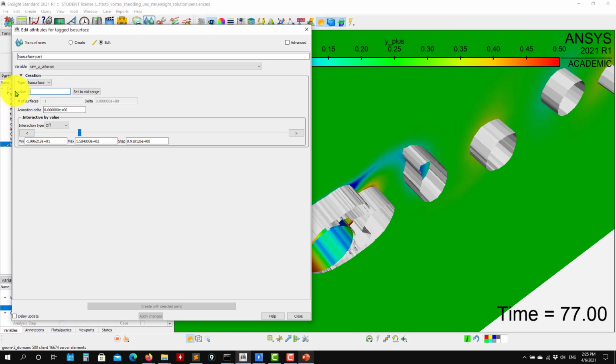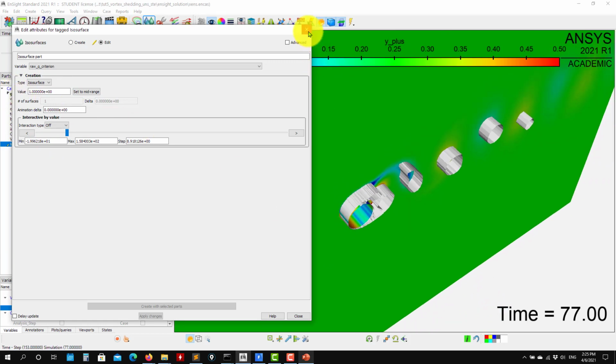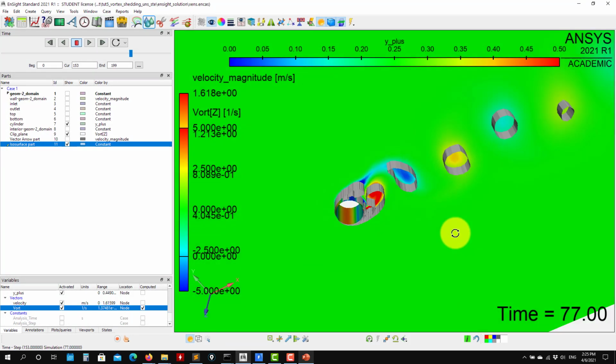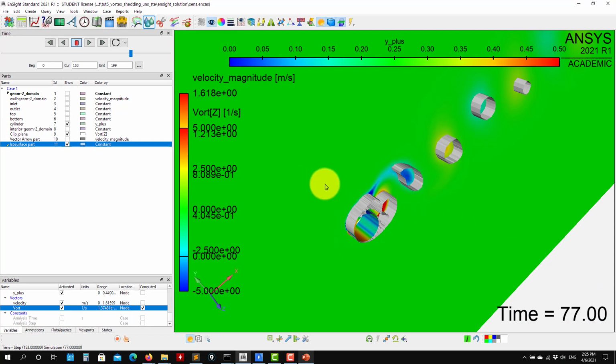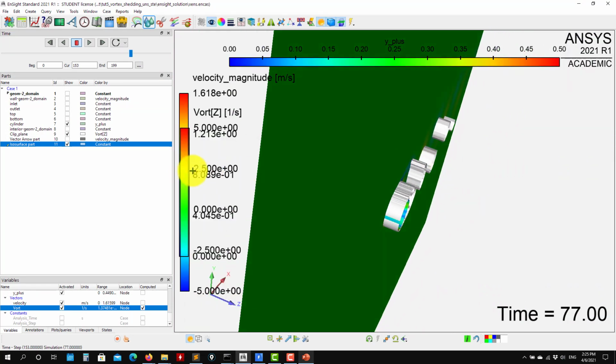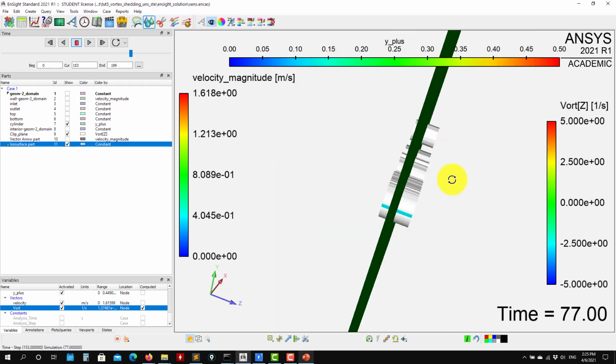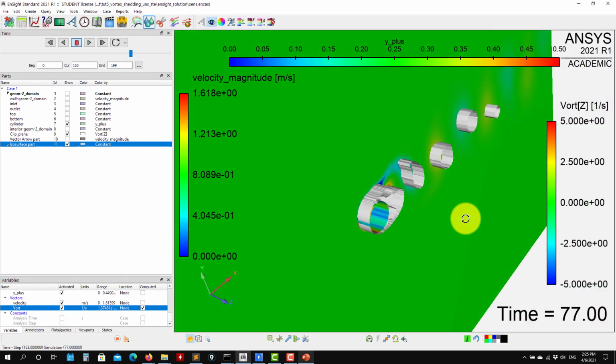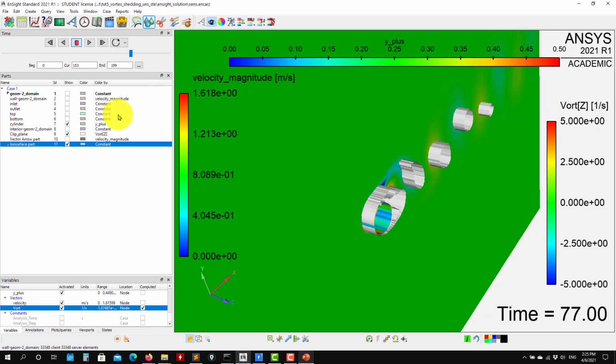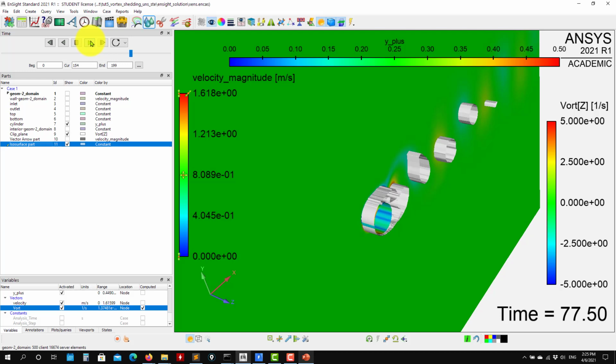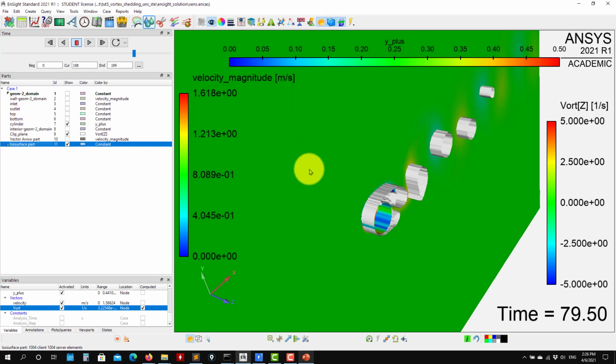So let me reduce. This one, the Q criterion, is really good to tell you where you have the vortical structures, okay? By the way, you can use Q criterion just when you have the third dimension, okay? In 2D, you will see the surfaces, but it works well using the vorticity, okay? Then that you have these isosurfaces, again, you can color by different colors, it's up to you, and you can animate everything. Okay, so you have many operations. What I show you here are the most basic ones, the ones that I use the most: clip plane, the isosurface, then vectors, create the cut planes.